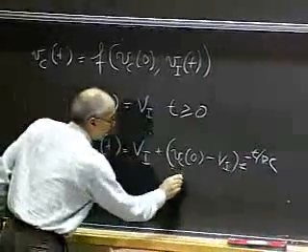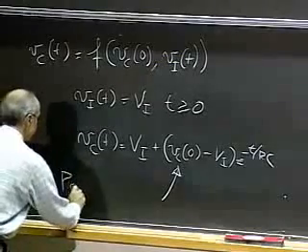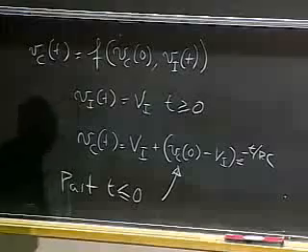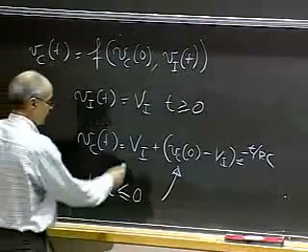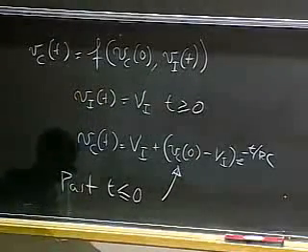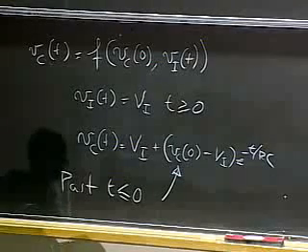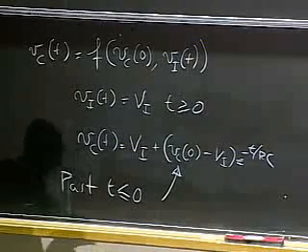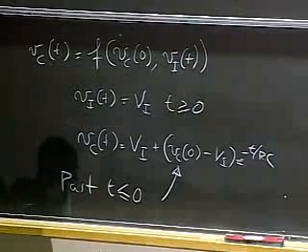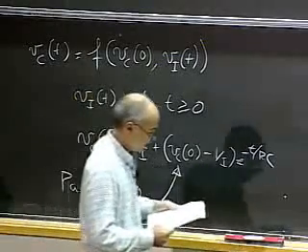So all the past inputs to the capacitor for time t less or equal to 0 is summarized in this value. And Vi being constant, the future is predicted from that. Okay? So that's the concept of the state. There's an initial state on the capacitor, and then there's a final state that will be reached when equilibrium actually is achieved.